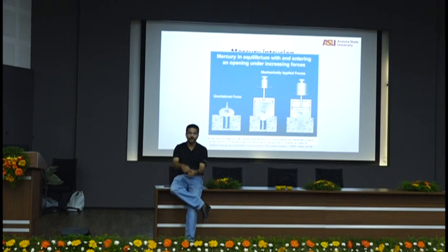When I told you about the unidimensional compression test yesterday, I told you what is actually failing the material? Tension because of Poisson's effect, where you have lateral expansion. But if I'm exerting this pressure all around, there is no way for the Poisson effect to happen. Should it fail?